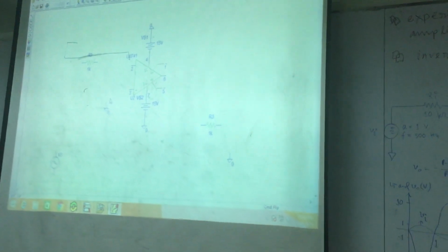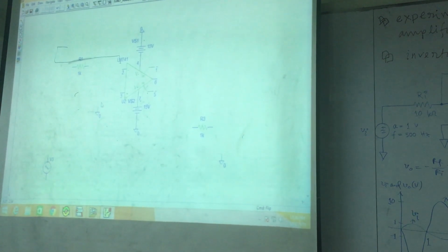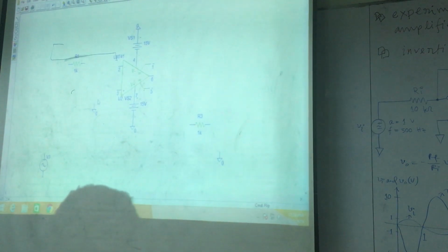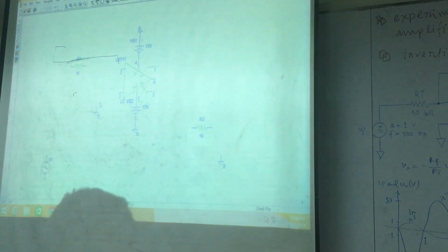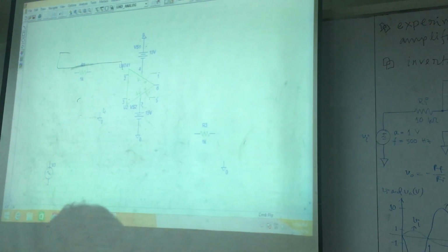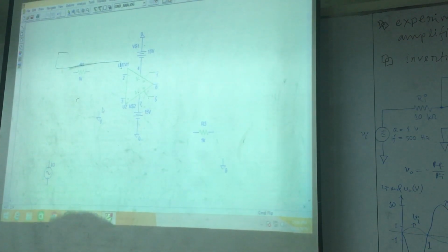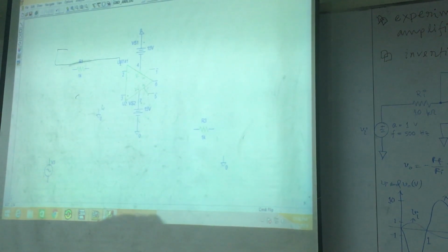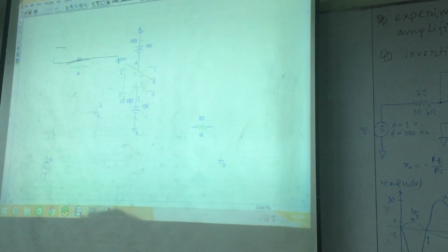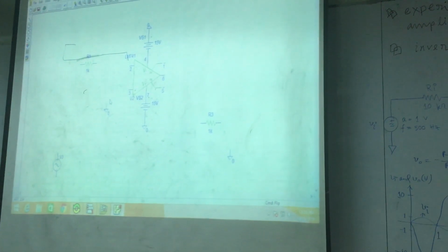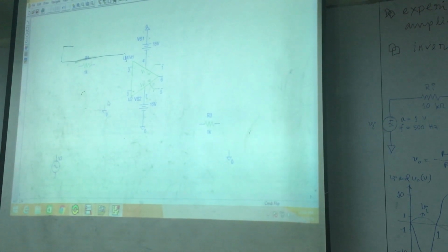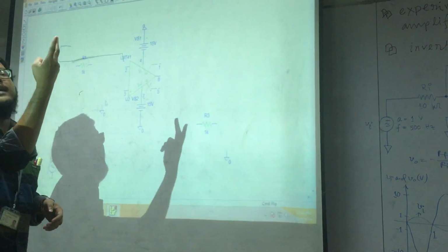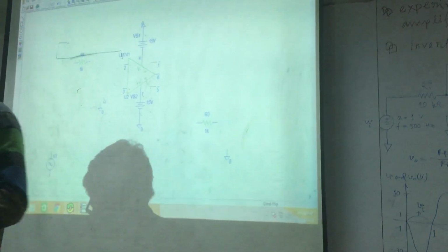Did you see what I did? I configured the triangle at first, then the power supply, and then I'm gonna go for the other items. Repeat this process, this procedure everywhere. Whenever you need to do something with the operation amplifier, get the operation amplifier. Fix it. Then attach power supply. Then go for some other connection, not the other way around. Okay? This is the basic practice. How did I get it here? Flipping, Control F. Okay?